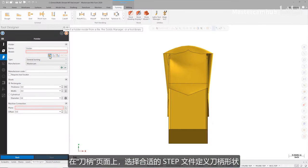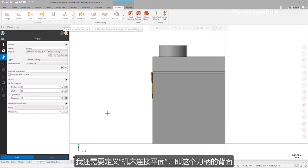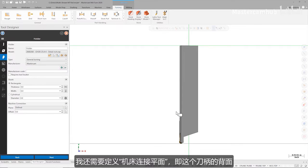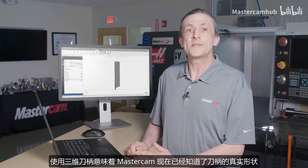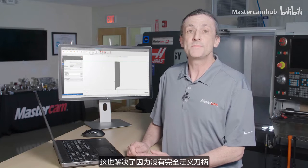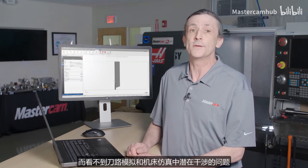On the holders page, I select the STEP file that defines the shape of my holder. I also need to define the machine connection plane, which is the rear face of this holder. Using a 3D holder means that Mastercam is now aware of the true shape of the holder, so false collisions like the one we looked at earlier are no longer an issue. Additionally, this means that collisions we may not have seen in backplot simulation due to an underdefined tool holder are no longer an issue either.